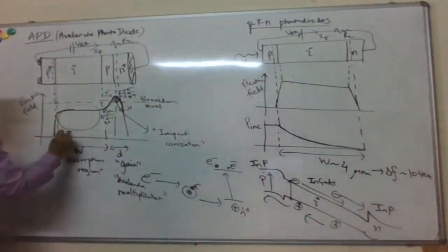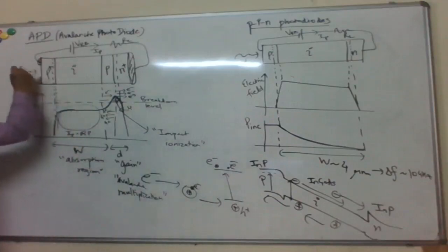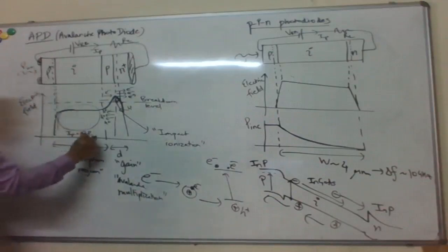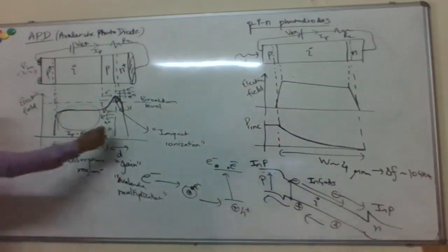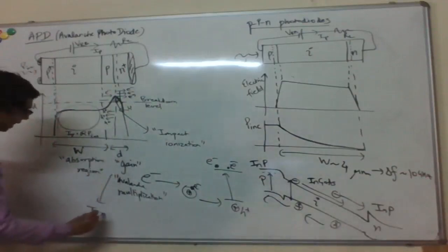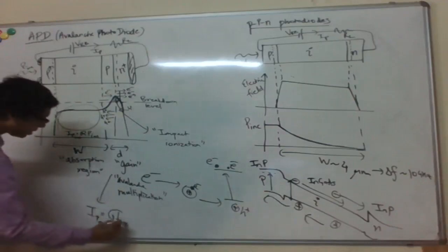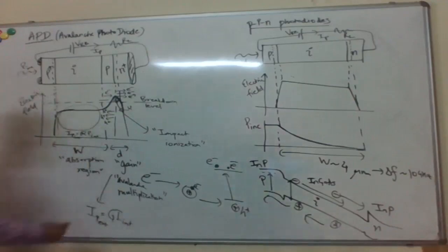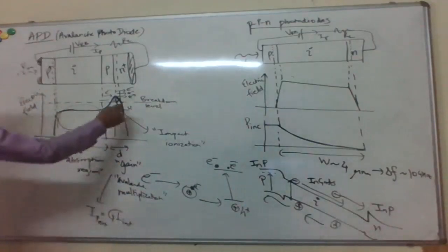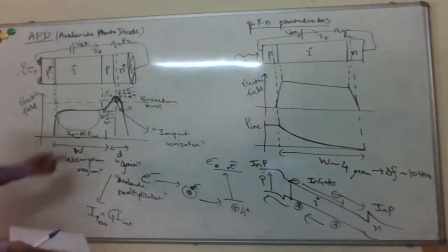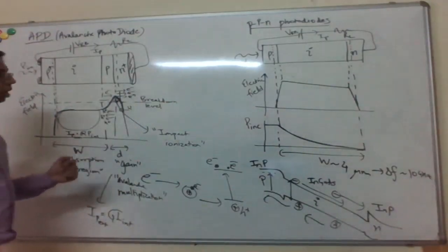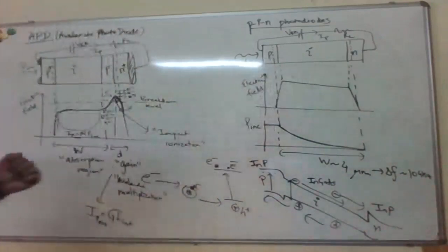Okay, so you can imagine like the primary photocurrent you generate here is something like responsivity times the incident power. Okay, and then in this region here, basically you have gain so that you multiply the photocurrent. So let's say this is some internal, then external. You multiply by a gain factor or a multiplication factor, which is much bigger than 1. So your effective photocurrent coming out, or the effective responsivity, will be much larger than the primary photocurrent.